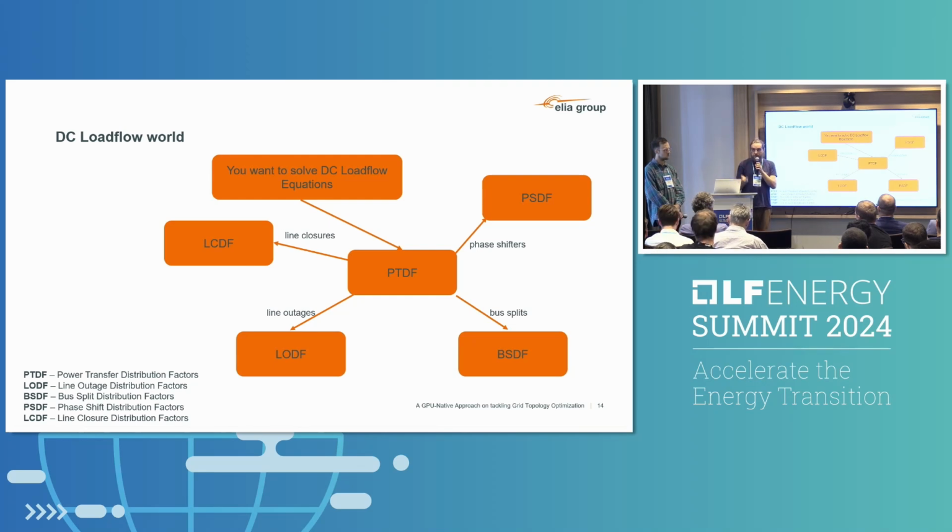So yes, we have implemented a full n-1 analysis, and for every individual topology, we actually compute a full n-1 analysis. Because it's fast enough, we don't even need to throw out n-1 cases. We can compute them all. So for every load flow, we basically multiply our computation time by 2,000 to 3,000, computing all n-1 constraints which are computed in operation.